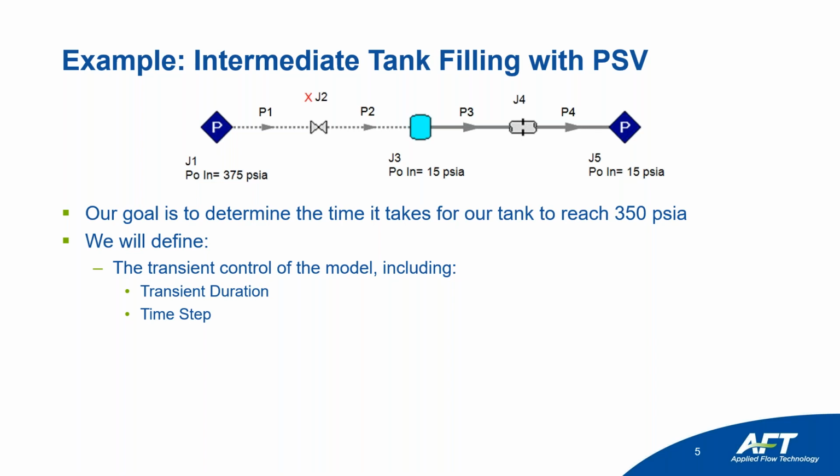So one of the things that you can control with the XTS module is how finely your resolution is for this modeling. Obviously, the smaller the time step, the more accurate your results are going to be because it's tracking that information more tightly. But that's going to come at the expense that you're going to run more and more different scenarios, right? So every time that you have a new time step, you're rerunning the model, especially if you have a very large system that might run into problems during your steady state analysis.